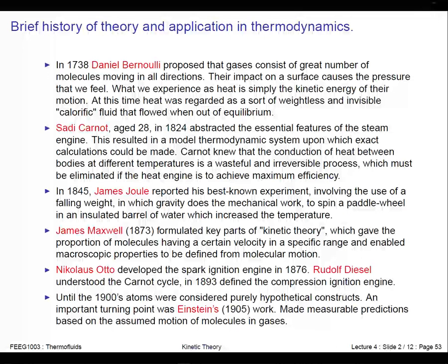So first came the spark ignition engine, or the petrol engine, and then later on the diesel engine came along, worked out by Rudolf Diesel. These two engines are quite interesting because the Otto cycle is theoretically more efficient than the diesel engine, but in the practical case, when you actually run a diesel engine, the diesel engine is actually more efficient because of the way you can operate it. And Rudolf Diesel understood what the Carnot cycle was trying to tell him, and so he sort of out-designed Nicholas Otto. And we'll talk about that in a few lectures' time.